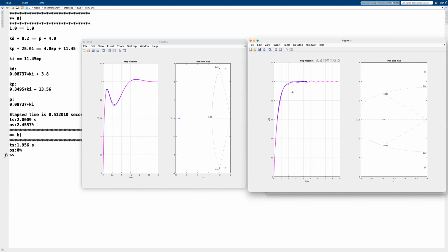It comes from the fact that the open loop has high oscillations. And this approach here, what we're trying to do by canceling poles and zeros, or by using this kind of pole zero placement here, which occurred naturally, of course, we didn't really decide on that, is actually something special. And it's called the notch filter, which is basically a band stop filter, and which tries to stop the frequencies for omega n, well, you guessed it, equals 5.01, because that's exactly what the frequency of our open loop oscillations are.